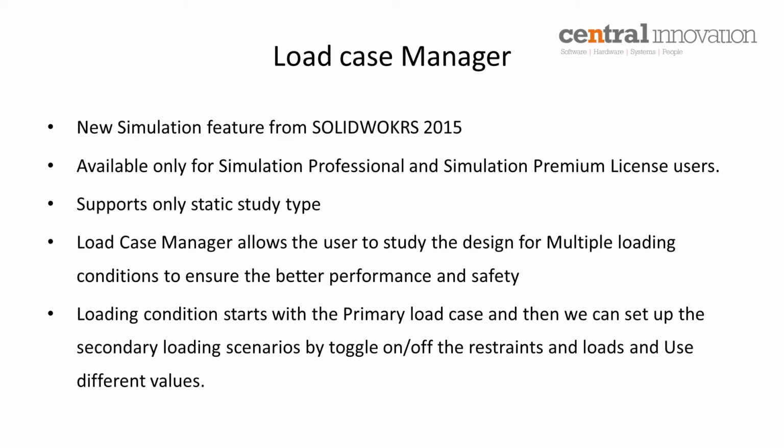From the table, you can easily manage. For example, I don't want to use a fixture and see how my design is responding. You can toggle off the fixture, and then I don't want to use all the loads. I want to use like 2 loads, or I want to include only the gravitational effect and see my design response. You can do that by using Load Case Manager.